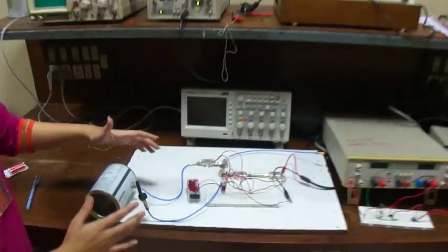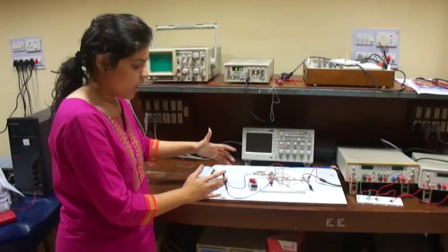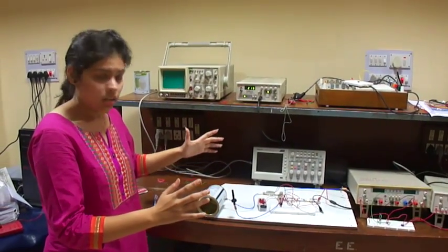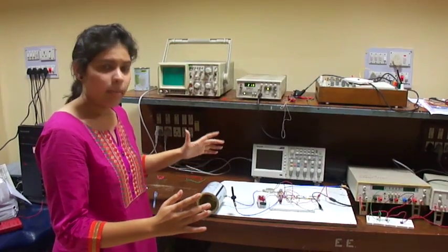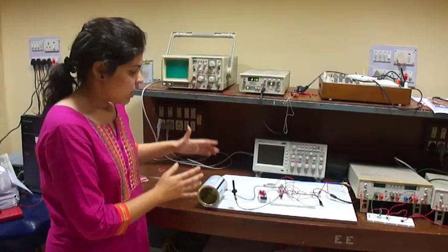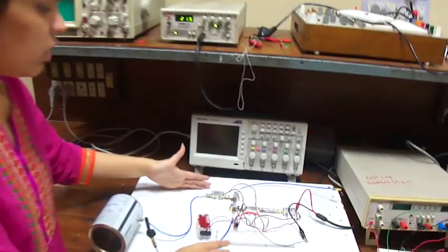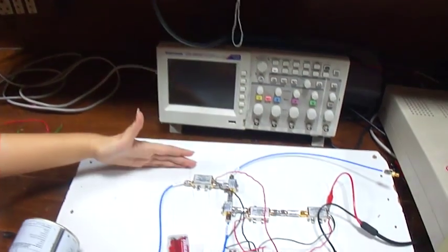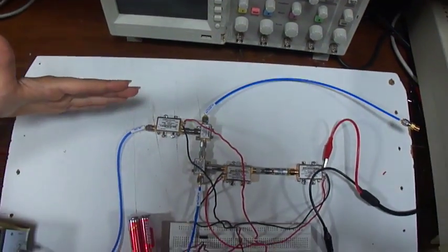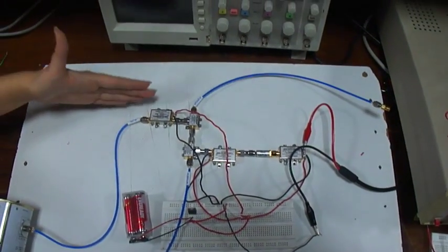Here, this antenna is from Texas Instruments. This will be radiating waves into the environment. Now, any waves which reflect back from an obstacle will be received by the receiver. The received signal is sent to a low noise amplifier. The low noise amplifier removes all the high frequency noises and also increases the power of the received signal, since the received signals are usually very weak.